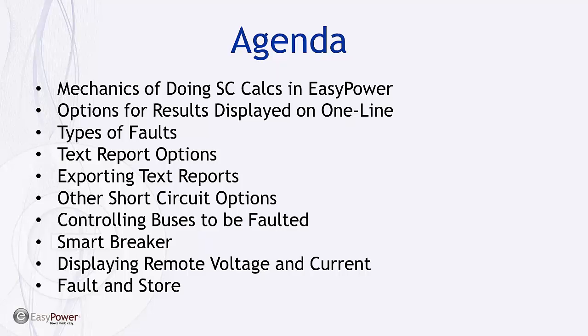We're going to look at the SmartBreaker feature, which allows you to open and close breakers and switches while you're in short circuit focus, to look at the impact of opening and closing breakers on the short circuit calcs. We'll look at another feature that's extremely useful called remote voltage and current. For any particular bus, you can look at the voltages and currents throughout the system for a fault on that particular bus. And we'll talk briefly at the end about the capability we have called fault and store, which allows you to display short circuit results in your panel schedules and MCC schedules.